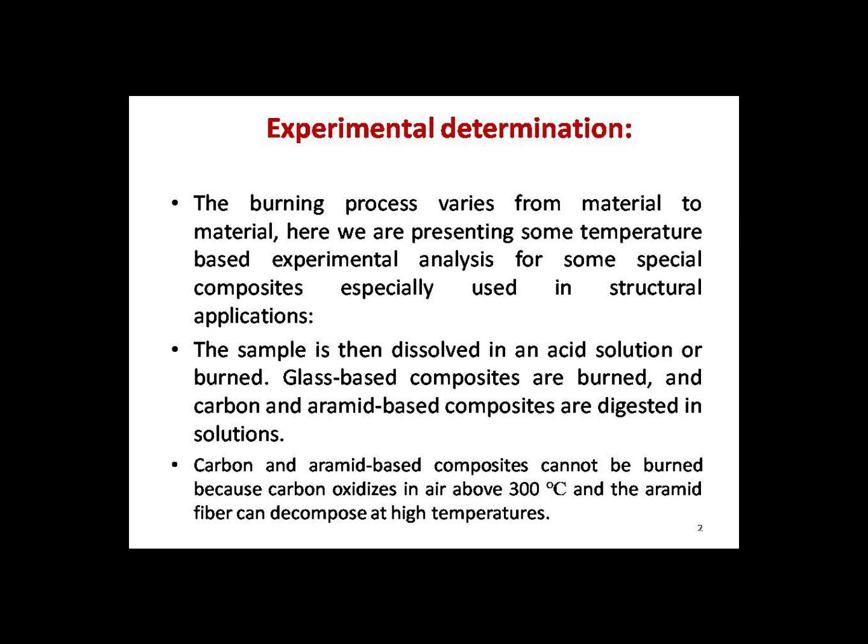And when we use carbon and aramid based composites, then these are to be digested in solutions. Carbon and aramid based composites cannot be burned because carbon oxidizes in air above 300 degrees Celsius and the aramid fiber can decompose at high temperatures.